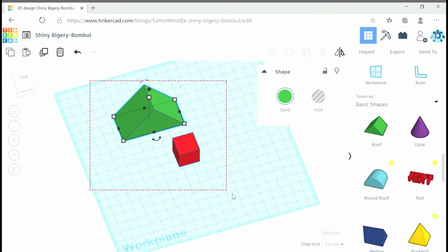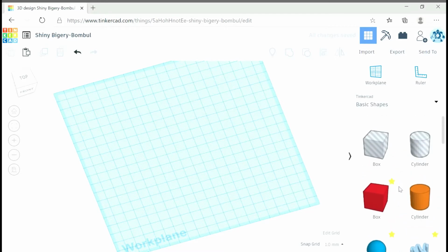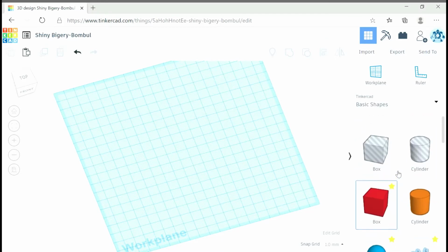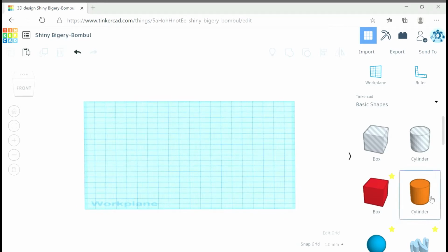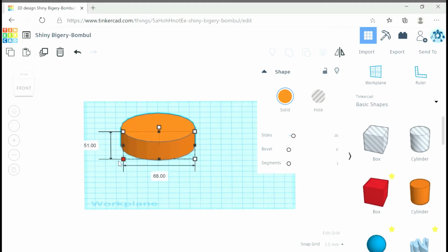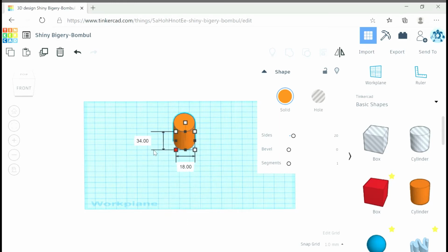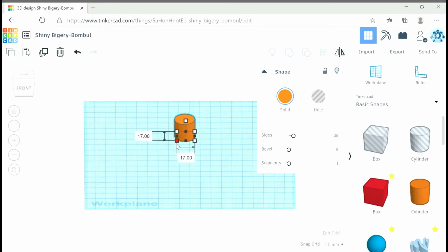So today, we're just going to make a really simple keychain using a base and the text tool. So the first tool we're going to learn is scale. So if we select our object and put it on the work plane, we have 5 squares here, which are all scale points. So if we grab those out, we can now skew it and change the size of it. If we hold down Shift while we do it, it will maintain its proportions. So we can scale it up and down proportionately.